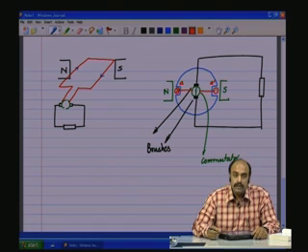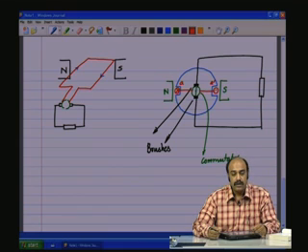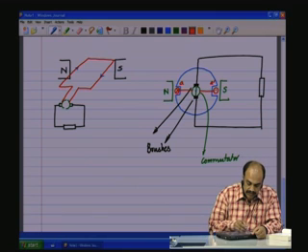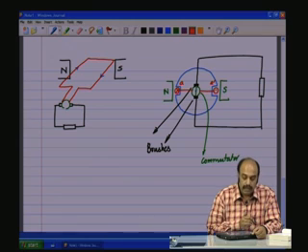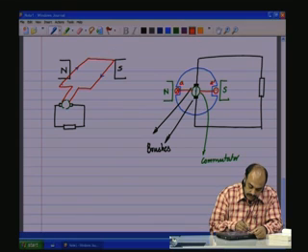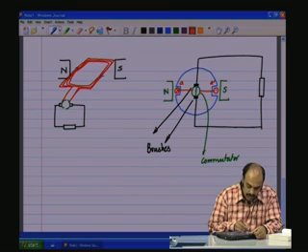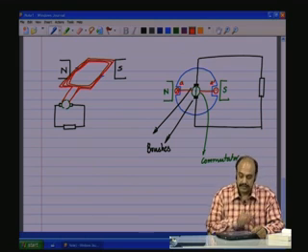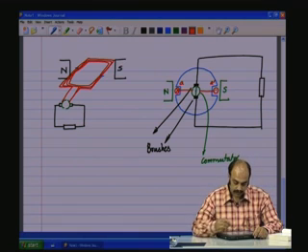Let us consolidate this concept or this idea of this DC machine with more coils. Also understand that a coil here, meaning that there is one conductor or one wire which is being routed through like this, but it could have many wires. It could have, like in a transformer, many windings like this, and the ends are brought out. Okay. So, keep that in mind. So, this is one coil with one set of conductors at diametrically opposite ends of the core.